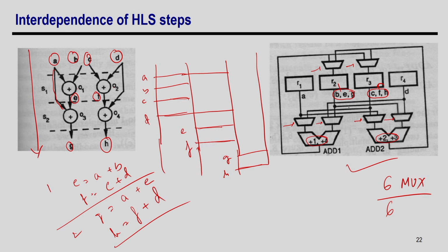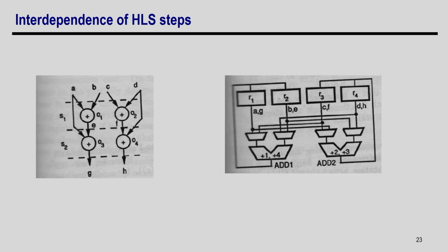Because this register allocation and binding is not the data path interconnection's job, this is done during the allocation and binding phase, right. So, if in the allocation and binding phase the binding happens like this, your interconnection cost, if I assume it by muxes and control signals, you need 6 control signals, 6 muxes. Okay. And then, based on this, another possible mapping is AG, B, CF.